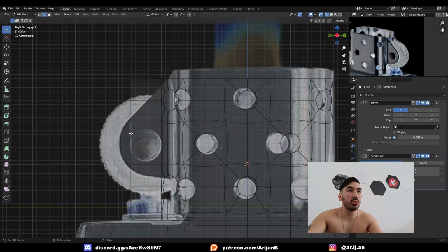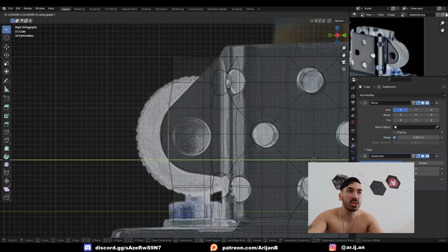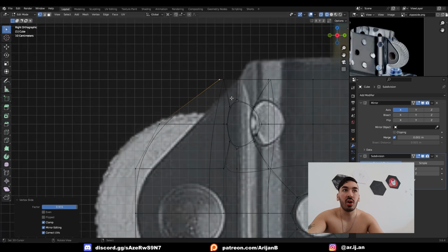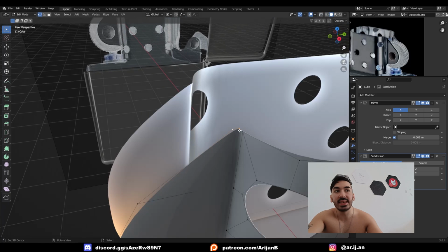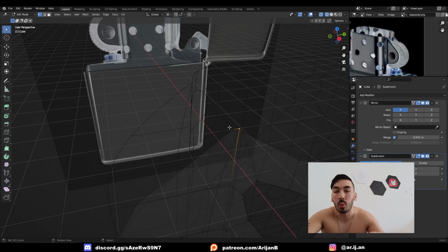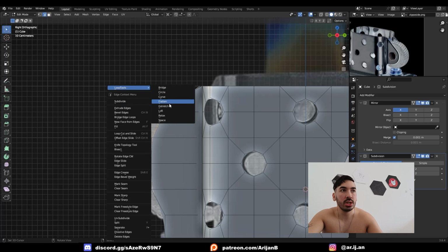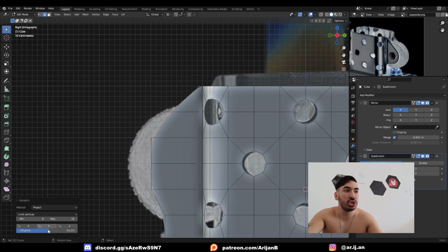In side view, I'm going to take these 2 edges and I'll bring them out as far as I have to bring them. Then I'll take this vertex at the top and slide it backwards as far as I can before it actually takes the exact same location as this vertex, because we don't want to merge those into one. Now I want to turn these 2 edges into a perfect straight line. So I'll go to W, Loop Tools, Stretch, and I'll set the type to project. That way if the influence is set all the way to 100, these are turned into a perfectly straight line.